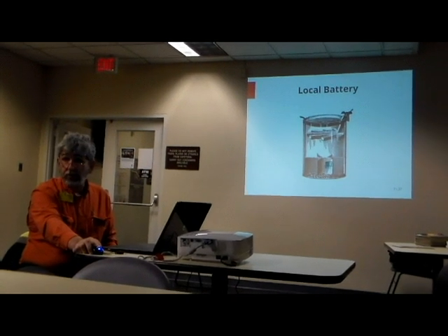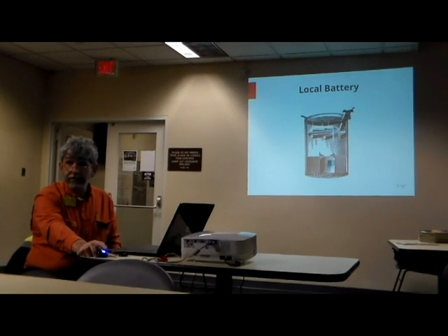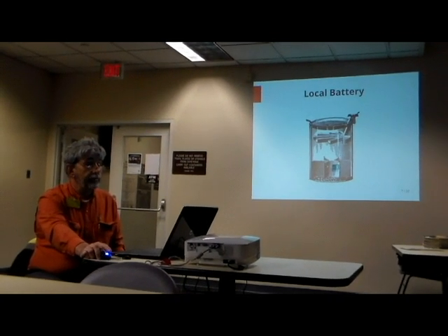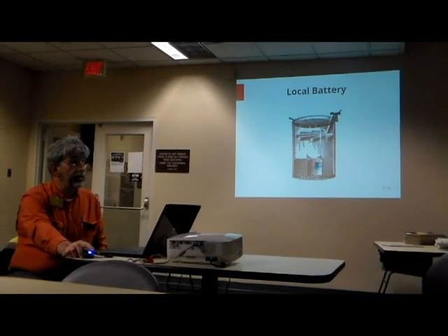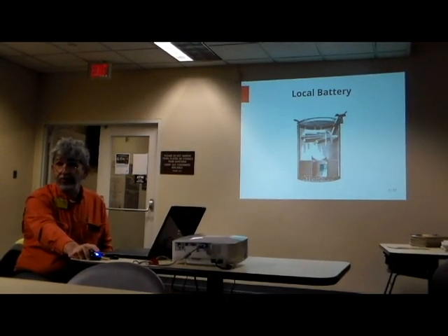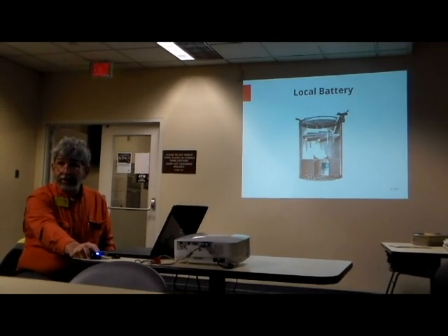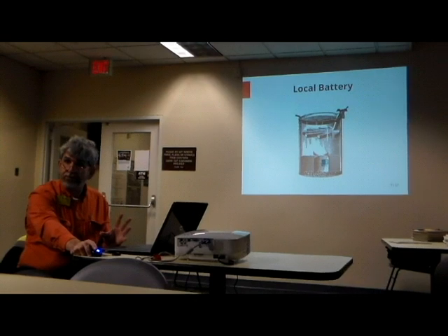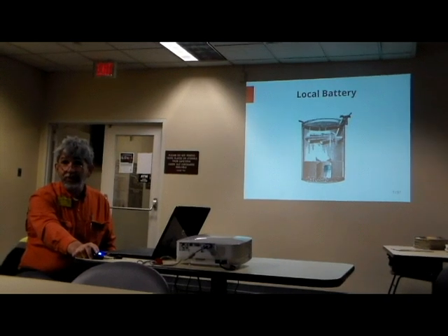The battery was commonly called, by the people who had to work with and on them, a crow's foot battery. This electrode right here looked enough like a crow's foot that it got that name and it stuck. This star-shaped piece down here is a copper plate electrode, and the wire that you see here has to be insulated because it passes through the opposing solution, and it would internally short the battery if it weren't well insulated. Each of these batteries produces almost exactly a volt. It depends on the strength of the solution at the exact moment you check it, but each volt you need is another one of these batteries.